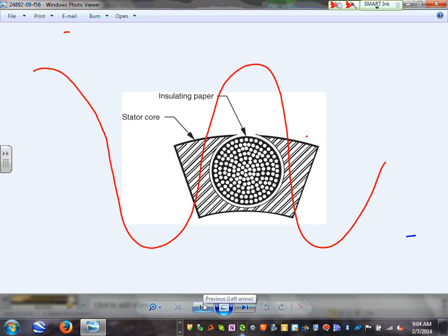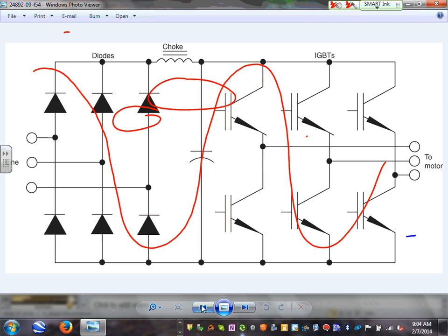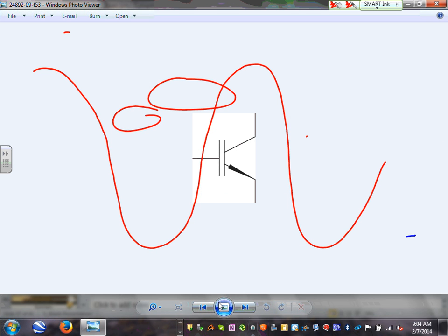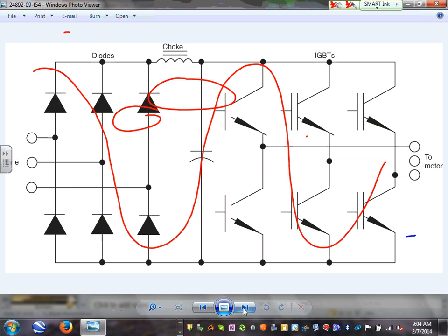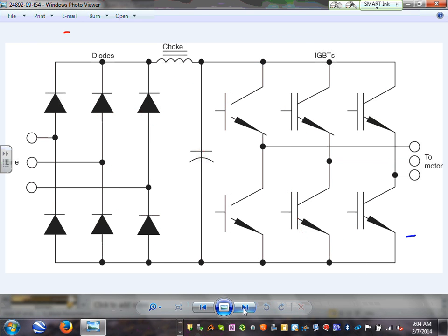Because of all this, guys, it creates heat inside the motor, so they start making the stator core insulation paper much better. You have to make inverter rated motors. They call them inverter rated motors. So that's basically the technology that you're going to be seeing.